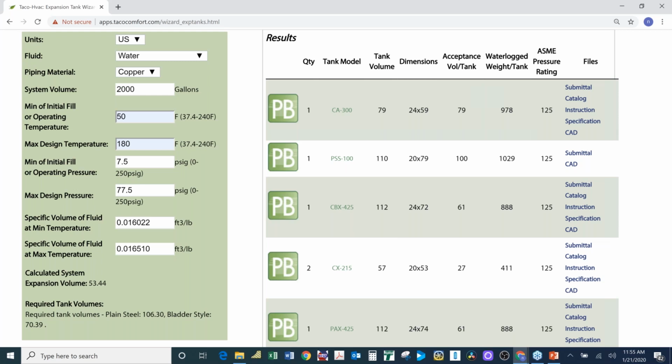That's correct. You can have as many expansion tanks as you like, as long as they're piped in parallel with each other and that the safety valves are in the proper location. Then you can have as many as you like. I was involved with a project out in Pennsylvania several years ago, and I think they had 4 1,200-gallon expansion tanks for a campus distribution system.